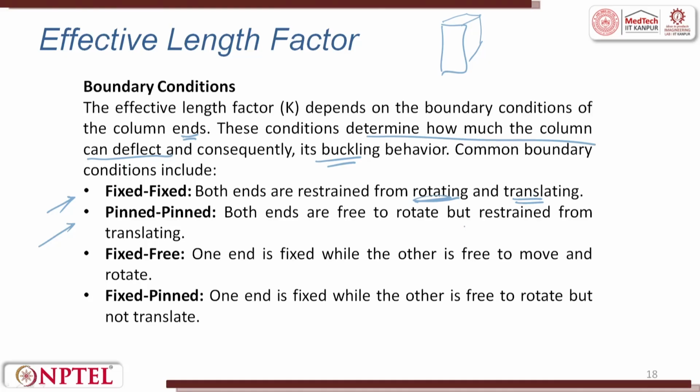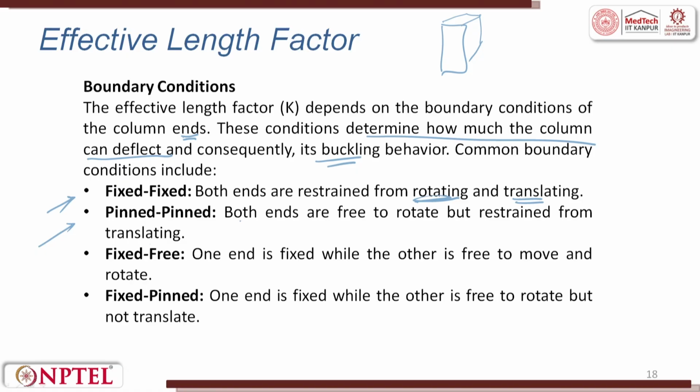When we have pinned, both ends are free to rotate, but restrained from translating alone. So, pinned means I am trying to pin it at the top portion, and pin it at the bottom portion. It gives you rotation, but never allows you to translate. That is the next boundary condition. The next one is fixed-free. One end is fixed, while the other end is free to move and rotate.